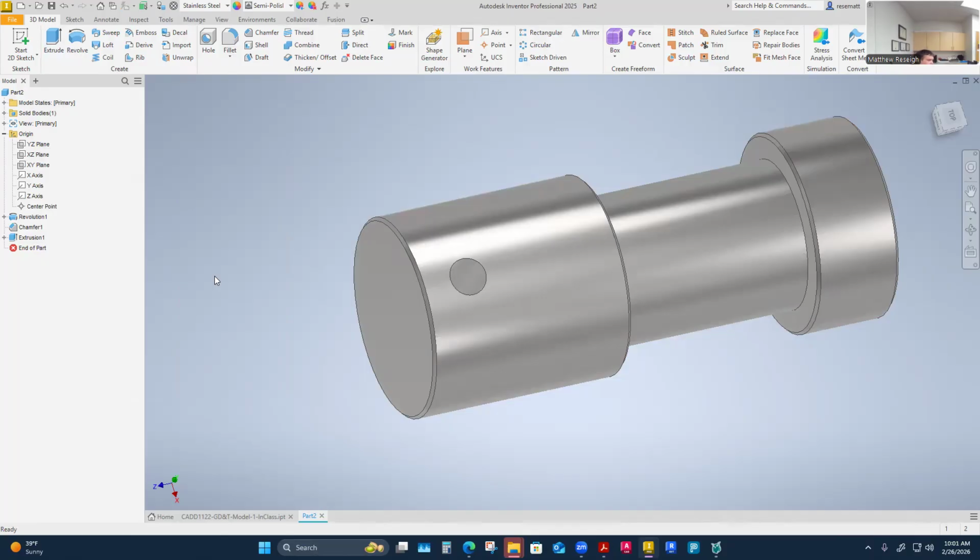And so they make a version of stainless steel that's generally unweldable but easier to machine, and it still has what we're looking for with stainless, which is generally some kind of corrosion protection against waters or acids. But there are even better stainless steels for if you have an acid that's going to attack this thing. They have increased nickel and chromium contents to be more resistant to acids. One of the most common generic stainless steels is 304.